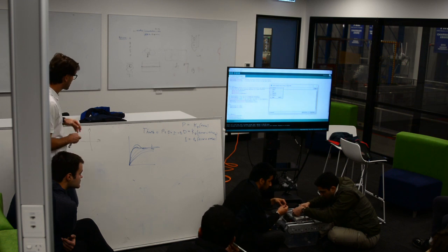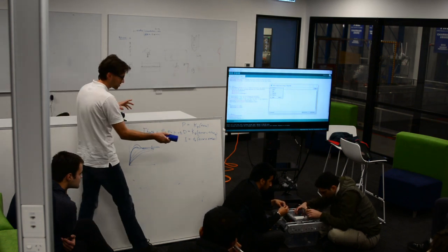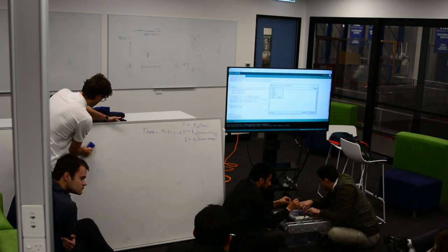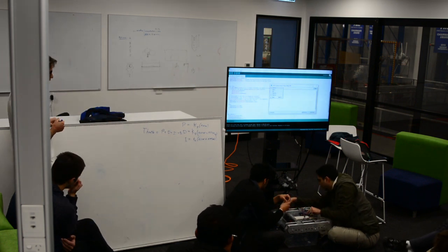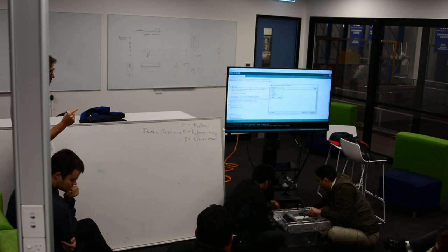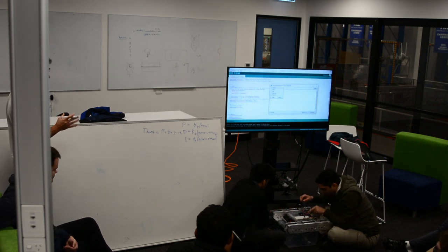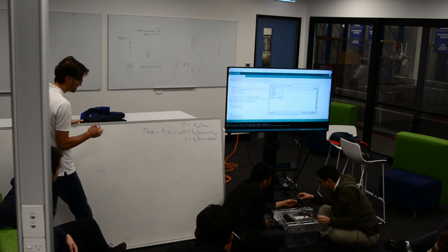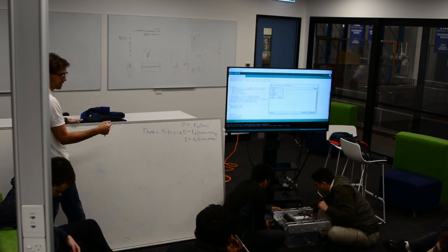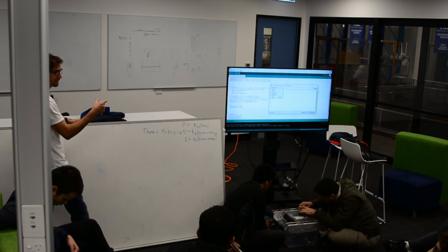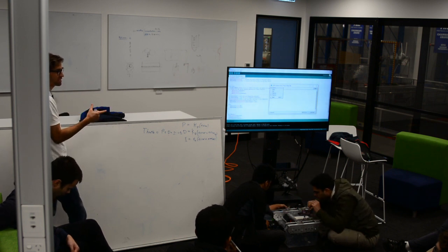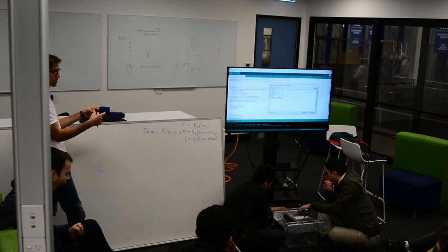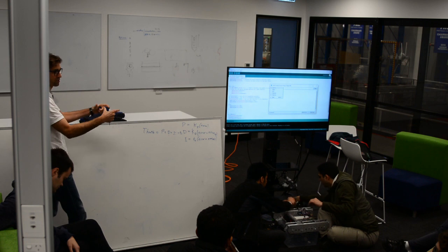So actually that's pretty much right. If we have a system where we want to do really good quality control, what we want to do is try and find a way so we never have a very large error. If we don't have a very large error, the way this is typically done is you send it small new commands. And the way you accelerate then is you send it slightly larger new commands. So let's say every 10 times a second you sent it a new position. The first time you send it a small change, the next time you send it a bigger change, and then a bigger change, and then a bigger change, and then maybe a bigger change.